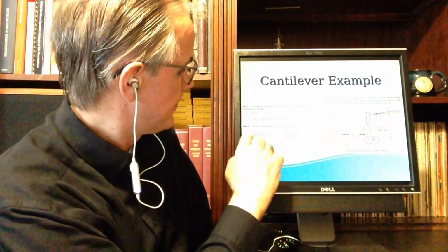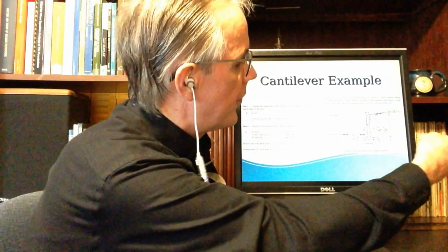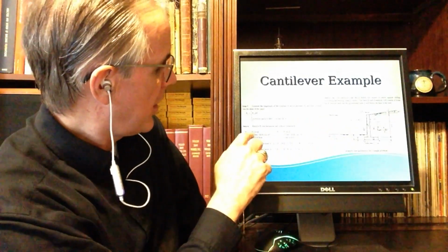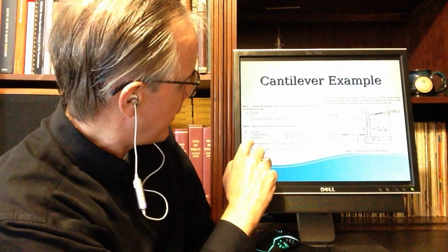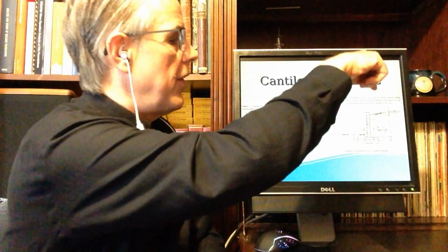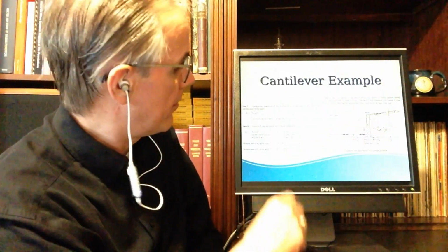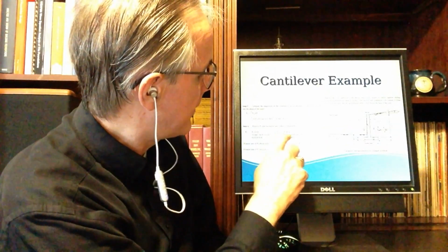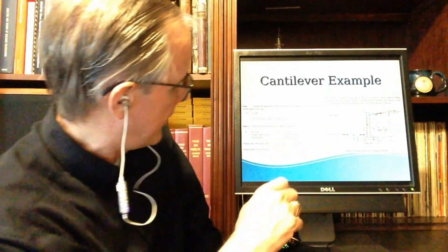Therefore the horizontal force, the force this way, is PA cosine beta. So you just multiply by cosine of 10, and you get 9,418. The vertical force, there's also a vertical component this way, and that becomes important, is PA sine beta: 9,564.2 times the sine of 10 is 1,660.